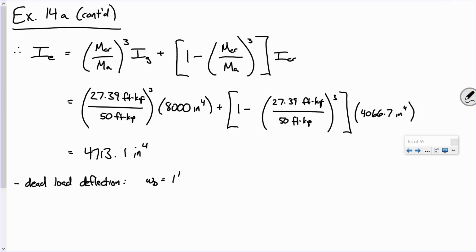It's 1 kip per foot, which, because I want everything in consistent units for what I'm about to do, I'm going to say that that's 0.083 kips per inch. Everybody know how I did that? I took it and divided it by 12, right? And then our length is, how long is the beam? Or 240 inches, right?